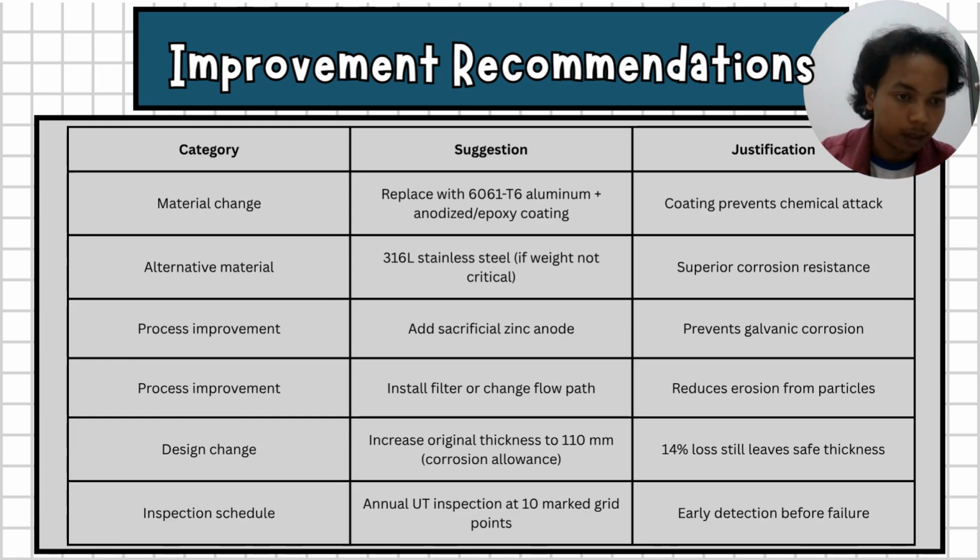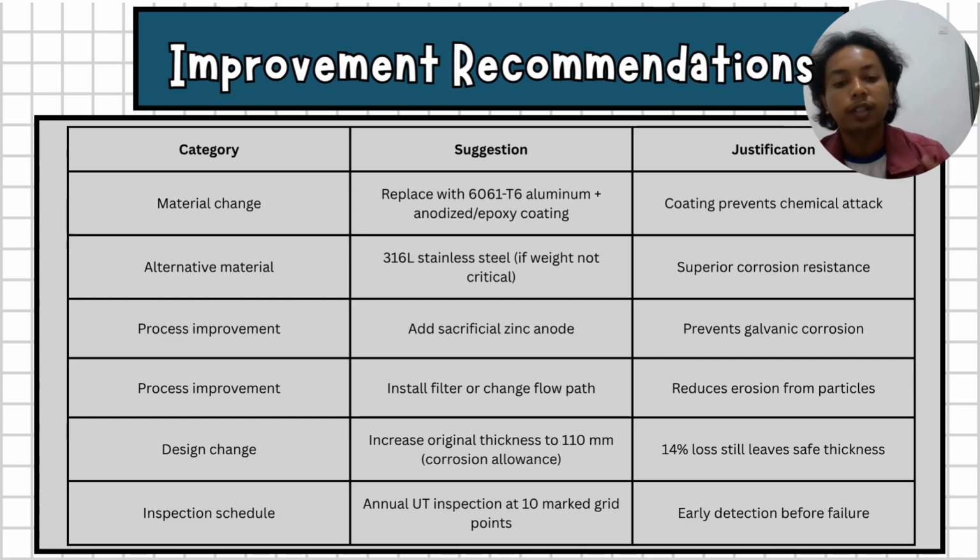So even after 14% wear, it's still safe. And the last one is inspection schedule. Check the thickness every year at 10 fixed spots to catch problems early.